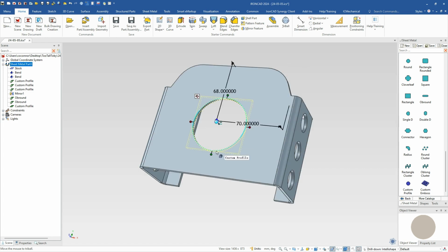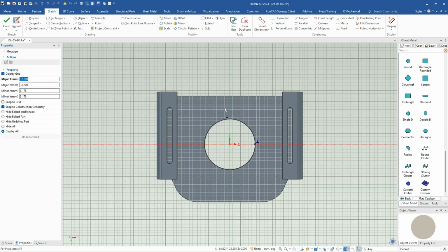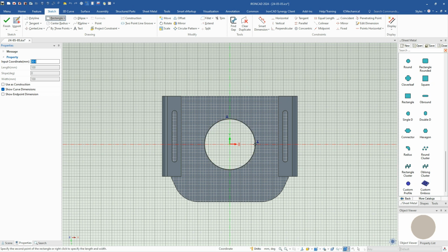So now that we've got that hole in the right location, we can do an Alt E to edit the cross section. Again, we want to draw it in this direction up here, so we're going to do a rectangle in this case. So we'll go ahead and hit this point here, move over, and I'm going to hold down until I get this little yellow dot there, so I can snap to that edge reference and pull it up to whatever height I want and just place that.